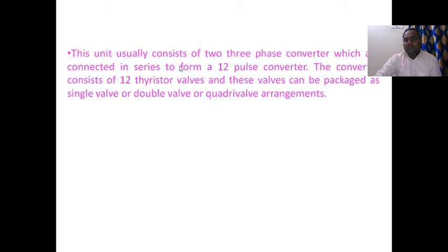This unit usually consists of two three-phase converters connected in series to form a 12 pulse converter.